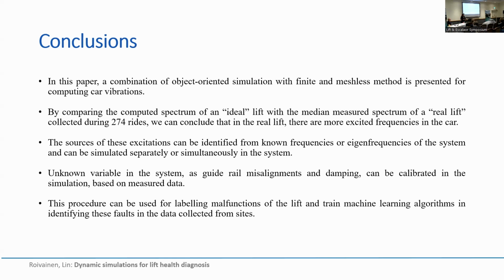Known variables like system damping or installation inaccuracy or other tolerances which are exceeding the prescription, the requirements, can be calibrated in the simulation based on measured data. And we can conclude that this procedure can be used for labeling malfunctions of the lift and training machine learning algorithms in identifying these faults in the data collected from the site.